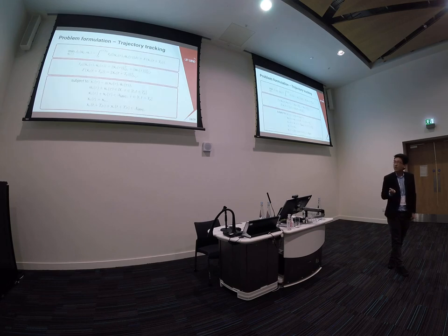So to track the reference trajectory, we minimize the error between the current state and the reference state, and the current input and the reference input from the previous problem. We also put the terminal cost, but notice that this work will not focus on the stability of MPC, which is an application of MPC. Subject to the aerodynamics, the input constraint, the state constraint, the initial state constraint, and the terminal state constraint.